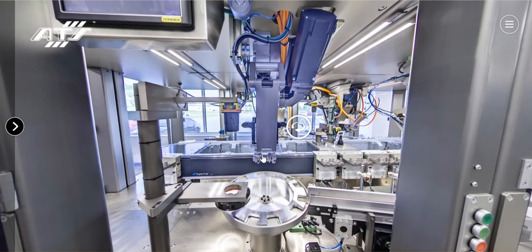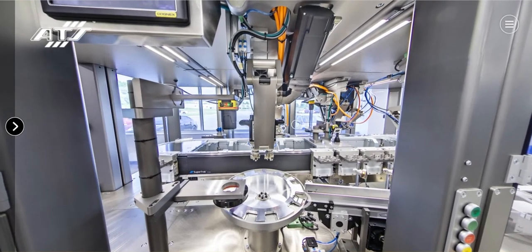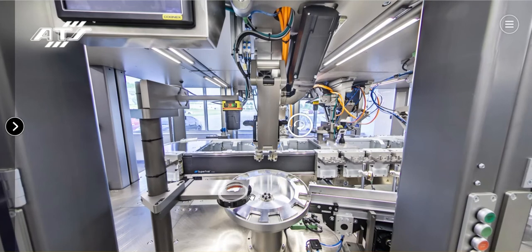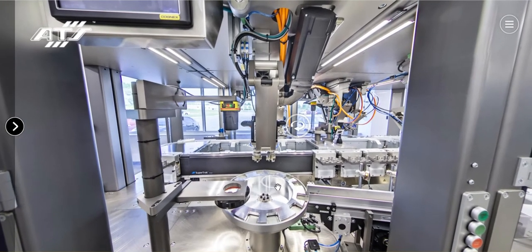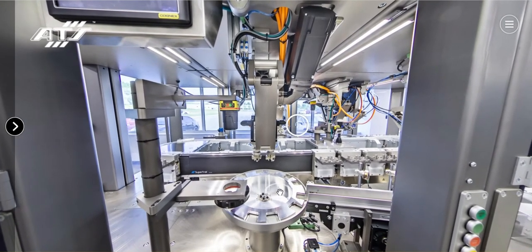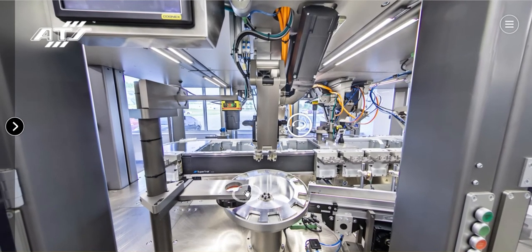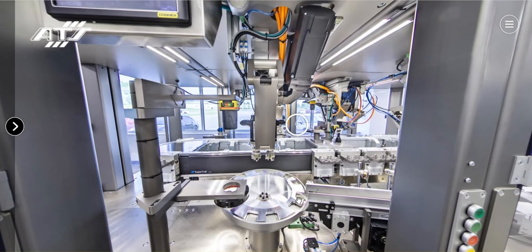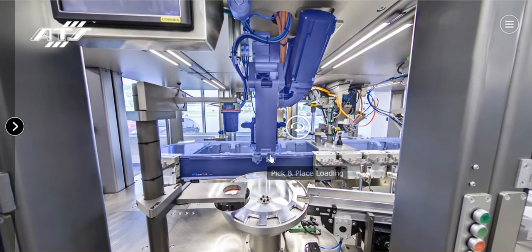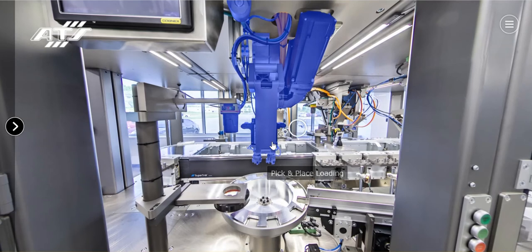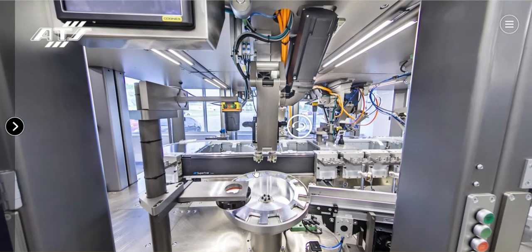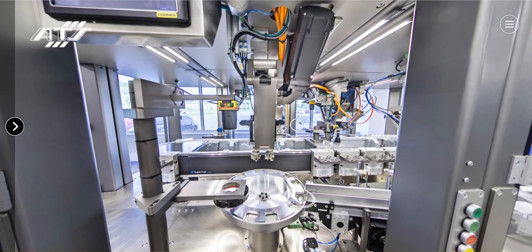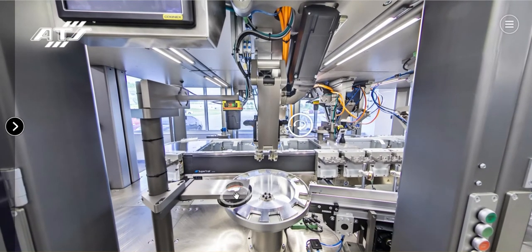You'll see as I play a video here momentarily that the part gets captured. This camera then, the disk is on a rotary servo, so the disk is rotated progressively around such that each part is presented to this camera. The camera takes a picture of the part, determining what radial orientation the part has to be in, because one of the characteristics of Symphoni is it can do both high-speed pick and placing and radial orientation at the same time.